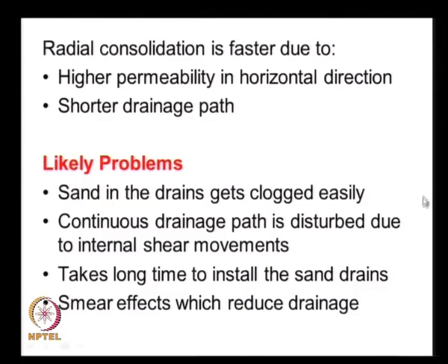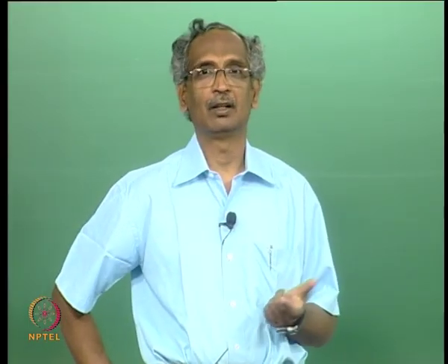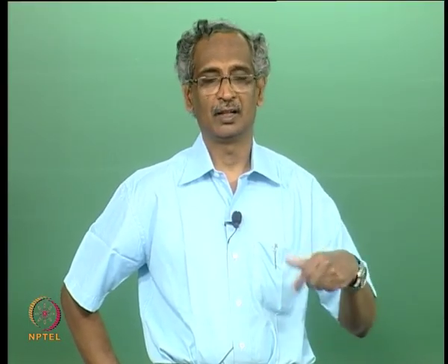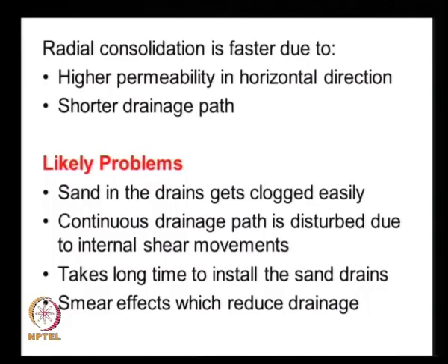And it takes a very long time to install the sand drains, because we need to first drill a borehole of certain diameter, like say 200 or some diameter as per our designs, up to the bottom of the soft clay layer, and then we have to fill that with sand of a certain gradation.